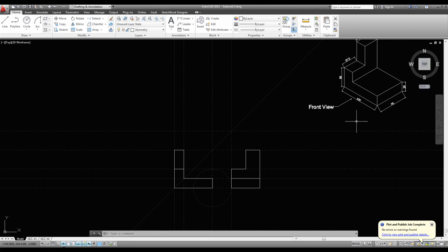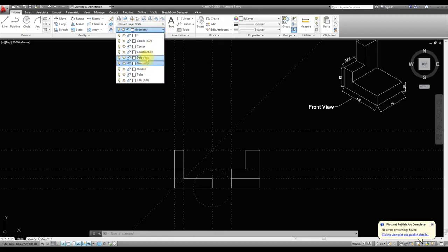From this side, we're looking, the front view is looking from this, where I've got the arrow, is the front view. In third angle projection, it's what you look at from this side is what you see here. So that we can see that edge, because you'll be able to see that line, which is this, and you'll be able to see that cutout. So that's the third angle projection for the right hand side view.